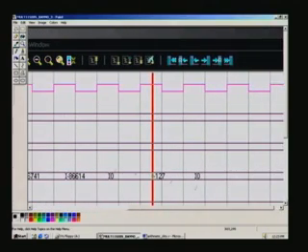So, this is basically the same, what we have seen, 0, minus 127. Final results are 0 into minus 1, that must be 0, that is what is here, and next one is 0 into 127, that merges with the same 0. So, it is continuing to be 0 here. So, this is the final result we had, and the result was delayed by 8 clock pulses because of 8 levels of pipelining, and this establishes the working of the algorithm.